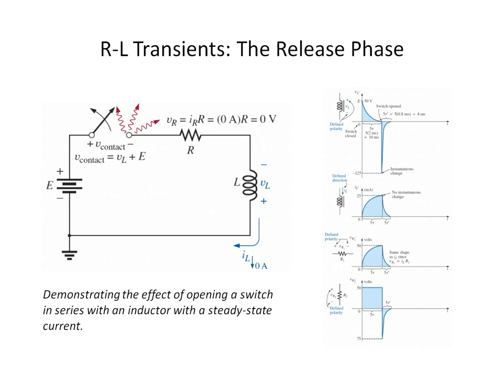So that's one thing to be aware of: the energy of the inductor is going to be sent back to the circuit, but as a voltage spike, and that voltage will exceed the voltage that charged it up to begin with, and it's going to return its energy in a polarity that is opposite to how it was charged.